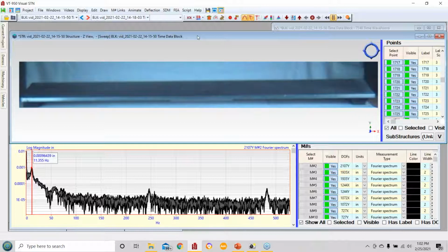There's my hammer, and I hit it, and you'll notice I hit it pretty hard. So it bounced. It's on little foam pieces on either side of the plate under here, so it's made to bounce. But the way you do modal testing, you don't hit it hard enough that the hammer stays on the structure for more than just a bounce. If you do, then you start double hitting and you get some corrupted data. And in my case, I lost one of my modes. It's around 100 hertz, but it's in the noise floor, so I couldn't find it.